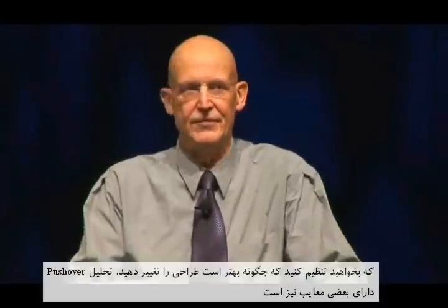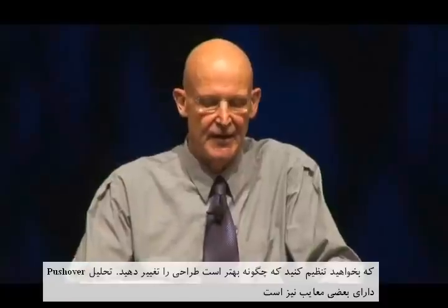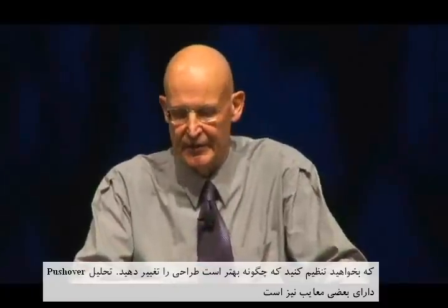One of the problems with dynamic analysis is you don't get any sensitivity information. So it's kind of difficult to figure out how maybe you should change your design. Pushover analysis has this little bit of an advantage.